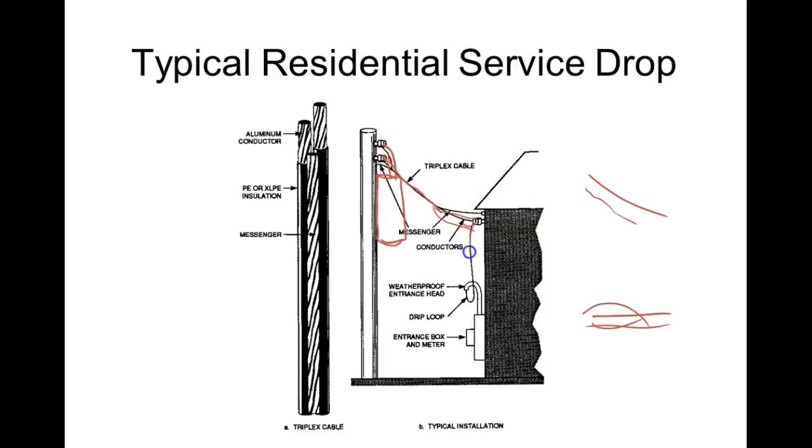Normally on your house, they'll run it down to your meter. And then you'll have another ground plug right here. Up here, the ground is established with a copper wire that comes down and runs into the ground by the pole where your transformer is at. So that's what they mean by triplex. So we have 2 insulated, and then 1 that's not insulated, because this ground is at ground potential, right? You understand that? So all power is Alabama Power, that voltage is looking for ground. Well, if that sucker's at ground potential, then we don't have to insulate that.